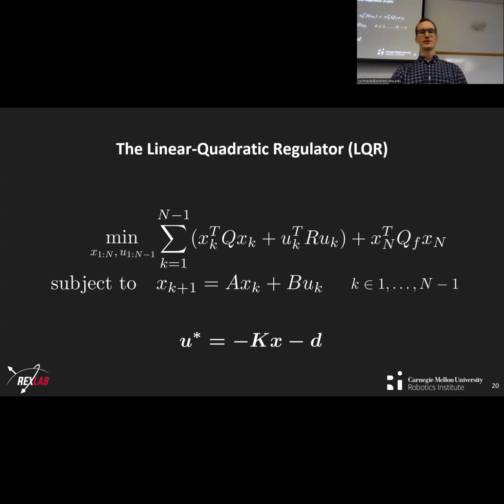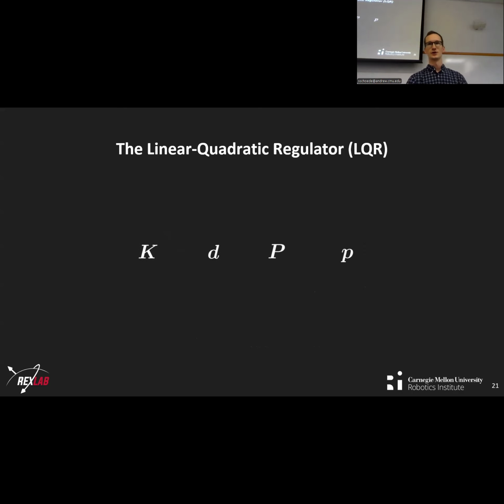And if we look a little bit farther into the Riccati recursion, because now we want to move on from the primal update, that's the new primal update that we're going to use, so we have to minimize this Riccati recursion complexity as much as possible. We see that Riccati recursion also gives us a few more matrices. It gives us this capital P, which is a cost to go Hessian, and it gives us the gradient term of that Hessian, which is lowercase p. And it gives us one of these for each time step in the horizon.